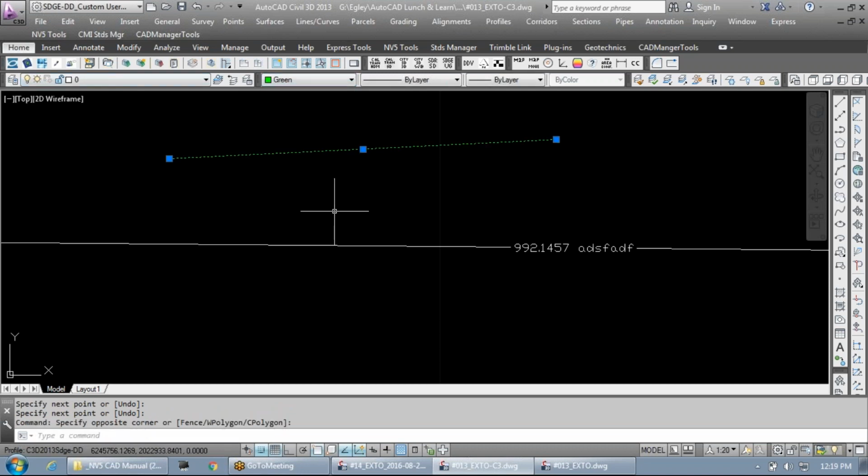But then they come in here and change the color like this. So now I don't really even expect this line to be on layer 0, right? Because it's green, and I know layer 0 should be white. So if you're in the practice of doing this, please stop it. This is kind of AutoCAD 101 and file etiquette.